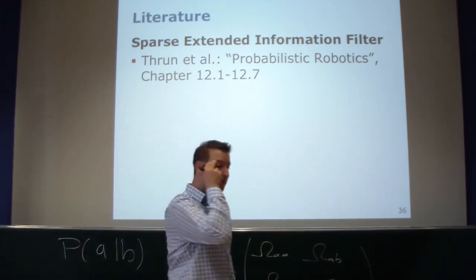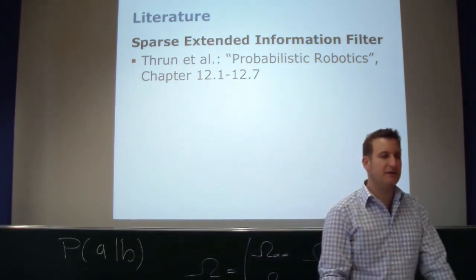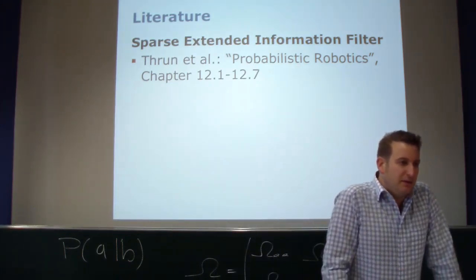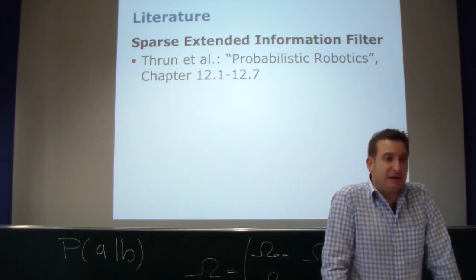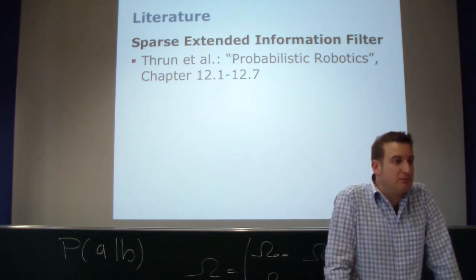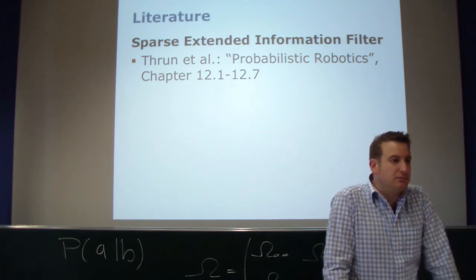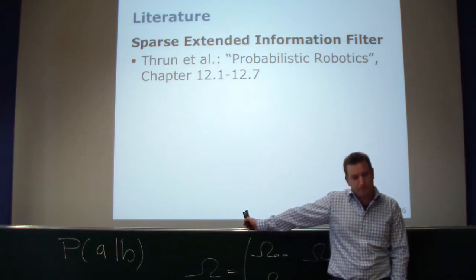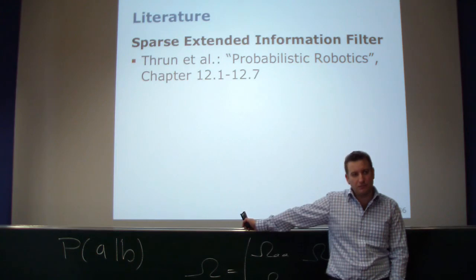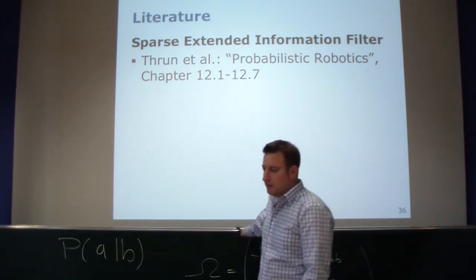Yes, please. If we observe 3 landmarks in the observation, do we replace all those 3 landmarks with the 3 others we have observed previously, and those 3 become passive, or do we choose? If you set the number of active landmarks to 3, that would happen. Is there any possibility to miss any landmarks because they are close to each other and we observe them at the same time, and we do one by one passive and active? It depends a bit on how you execute your SEIF.